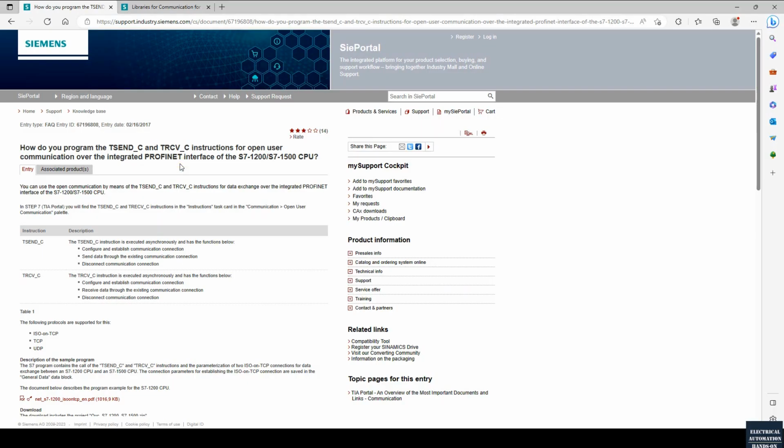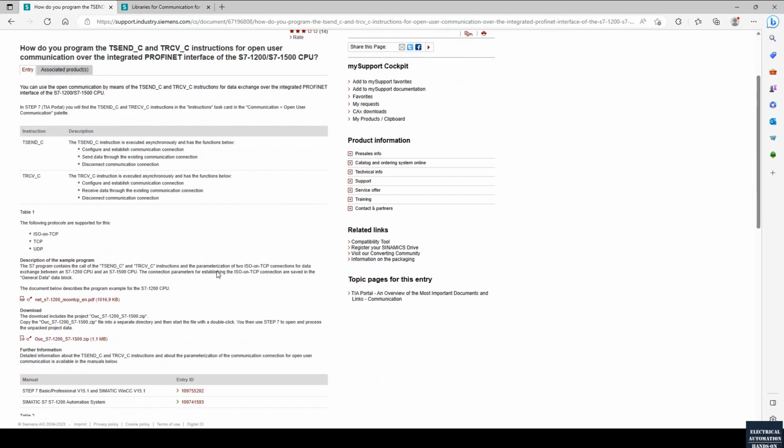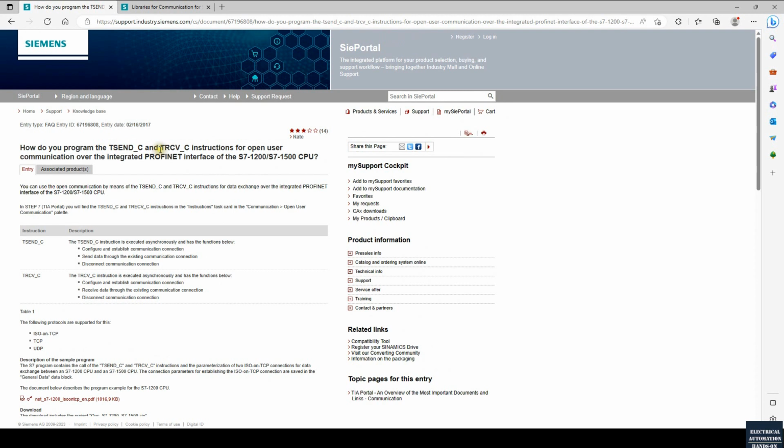In the previous video, I talked about how we can use TSEND and TRECEIVE, the traditional way to implement TCP/IP communication. As we discussed, while we are using TSEND and TRECEIVE, these two function blocks will occupy the communication port respectively. So if we have one device that needs to send and receive running at the same time, we need to prepare two ports, one TCP/IP port for send and one TCP/IP port for receive. This device needs to provide two ports respectively for send and receive.